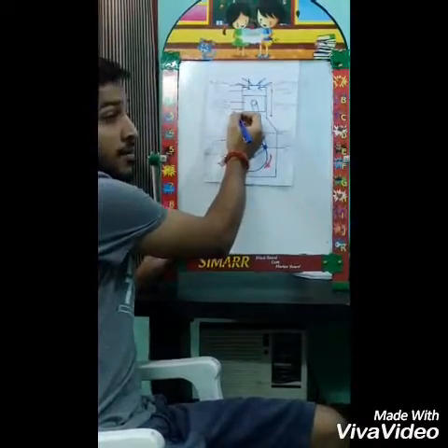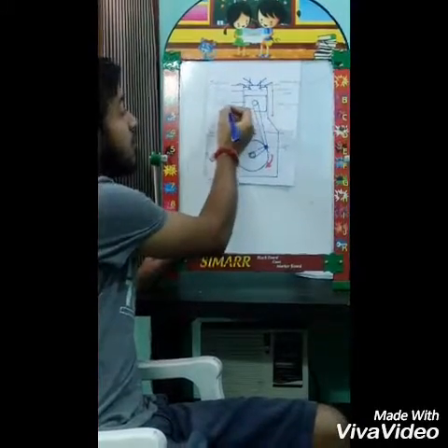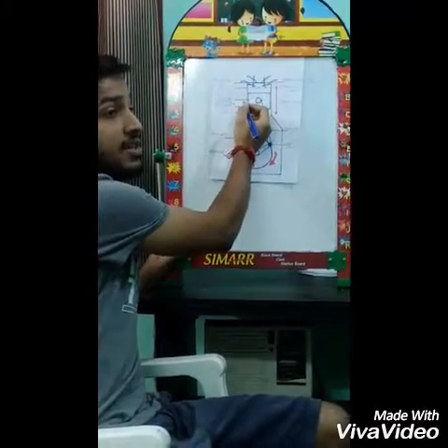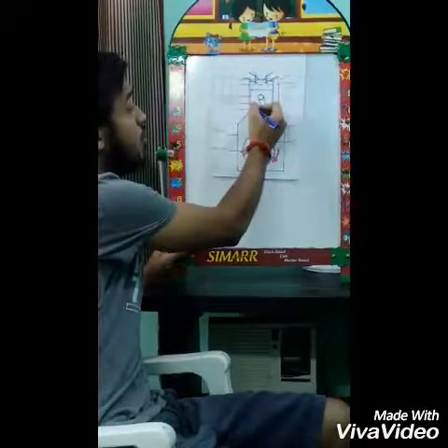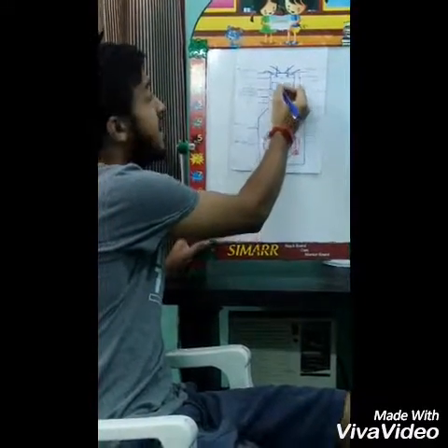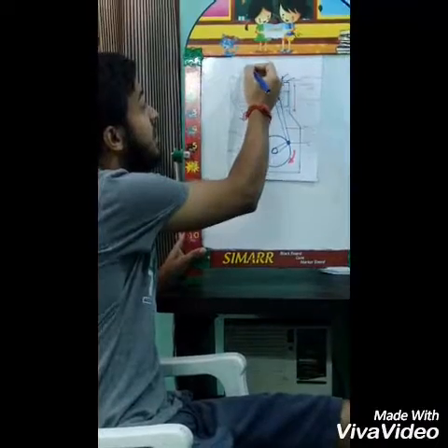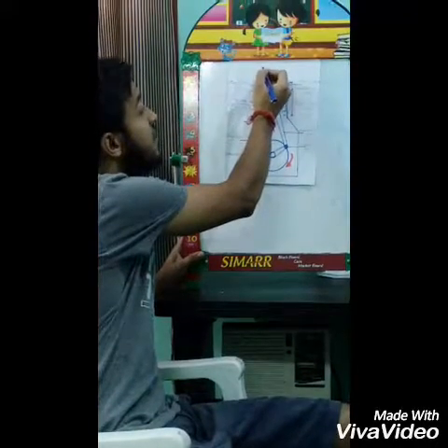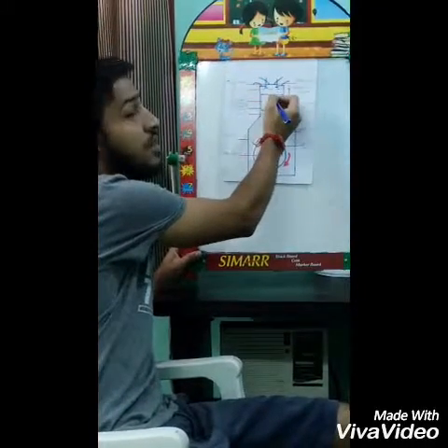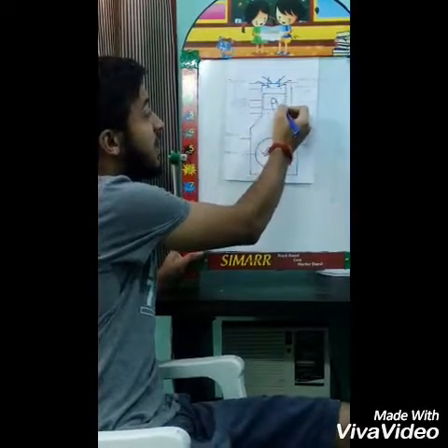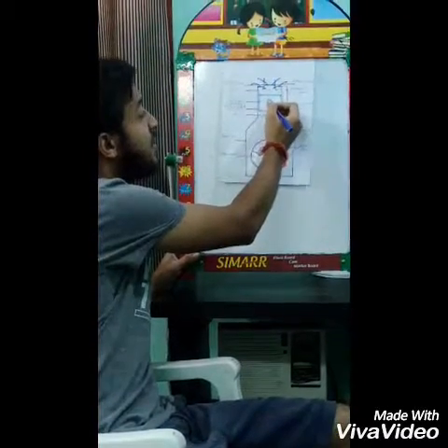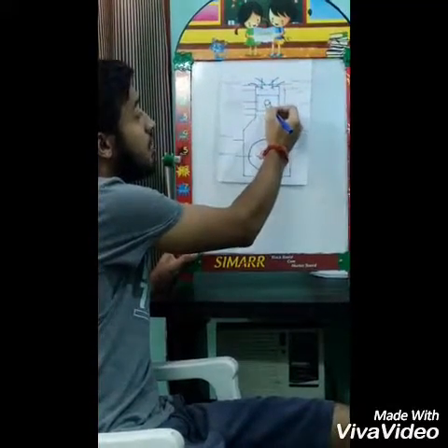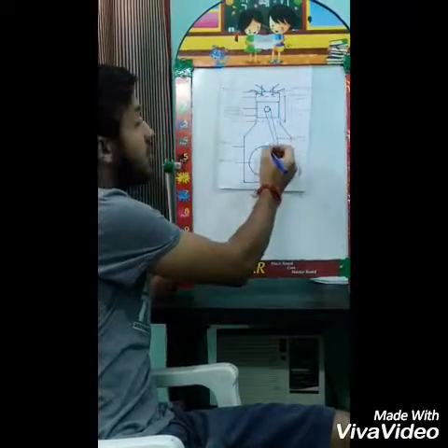Talking about the piston in an IC engine, the purpose is to transfer the force from the expanding gas, that is the air fuel mixture that comes from the inlet valve. When it expands, the force is transmitted by the piston from the cylinder to the crankcase.